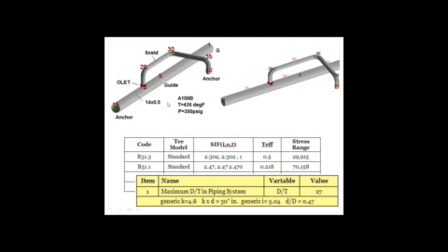So if we go to the next slide, here's a D over T value of 27. Here's the K over D, relatively small. But the reason you would use FEA tools in this case is not because of the D over T ratios or because of the effective lengths, but because the FEA tools has corrected the OLET SIFs. In WRC 329, Rodabaugh pointed out that the OLET SIFs in the B31.3 code today were off by about 2, and so that has been corrected.